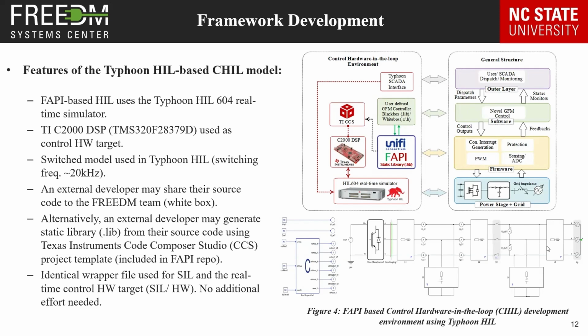Prior to starting the HIL simulation, the CCS project code needs to be loaded to the DSP. During runtime, the user-defined GFM control sends reference to FAPI. FAPI generates the PWM signal from the DSP and actuates the switches of the power stage.